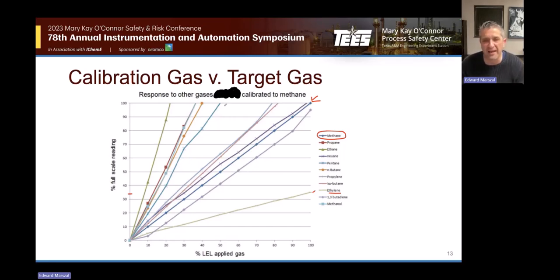Whereas if you compare that against this line here for pentane, this line's a little bit wonky. It's not a curve, but it's a little bit wonky. And even this line here for 1,3-butadiene has a couple of wonky points. So we lost our linearity there, and we lost our linearity here. But between 10% and 90%, it still looks pretty linear. So again, you're going to need to do the same thing that I talked about on the previous slide in terms of that calibration point.